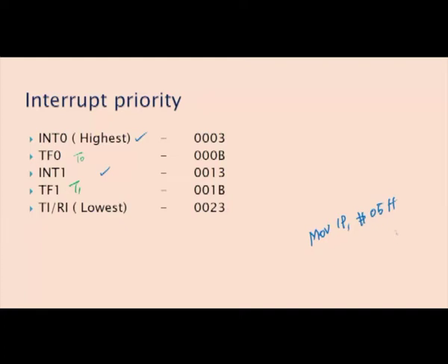I have inserted one pen drive and one CD or other peripheral devices, or I have interfaced with the LED blinking, 2 sensors are connected. If any signals are sensed, then automatically it will raise the high signal on INT0 and INT1. So at the same time both sense the signal and activate the high signal. Now the microcontroller will decide, first it has to perform the INT0 request. Suppose sensor 1 is connected, means its request is serviced, then only it goes to INT1.